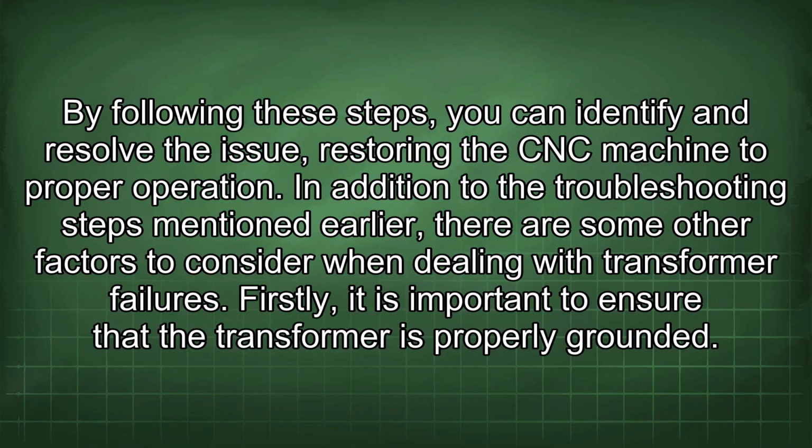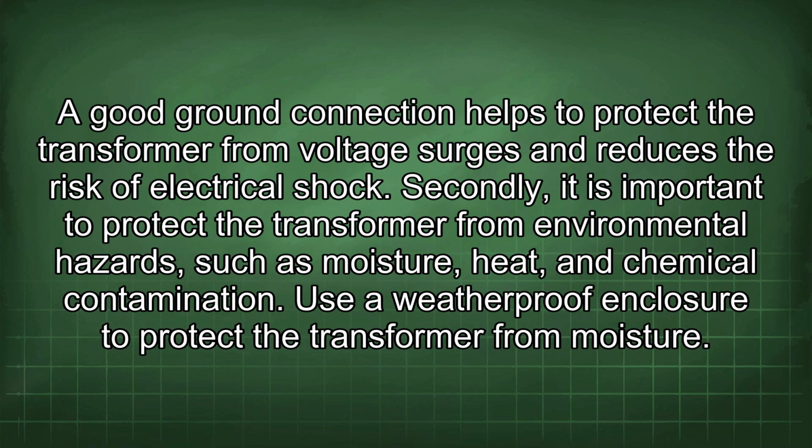In addition to the troubleshooting steps mentioned earlier, there are some other factors to consider when dealing with transformer failures. Firstly, it is important to ensure that the transformer is properly grounded. A good ground connection helps to protect the transformer from voltage surges and reduces the risk of electrical shock.